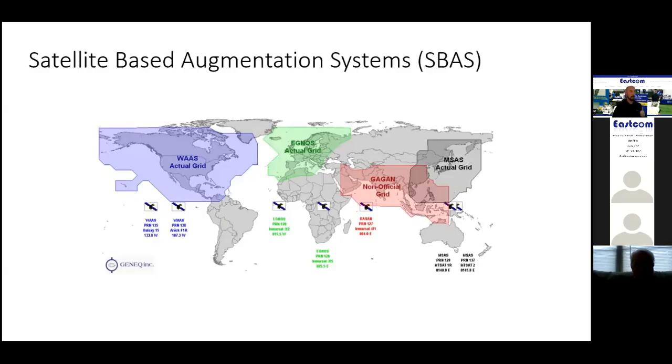It's highly recommended that any unit that you get, make sure it is SBAS corrected, because that's going to get you to the sub-meter accuracy in some cases if you're in the wide open, but not in all cases. So if you're not in the wide open, we're going to get into that later, you may not get that good of accuracy. So satellite signal is based on line of sight. If you get out of line of sight of the satellites, you're not going to get that good of a correction. So when you get under tree canopy, you get next to buildings, your accuracy is going to degrade.